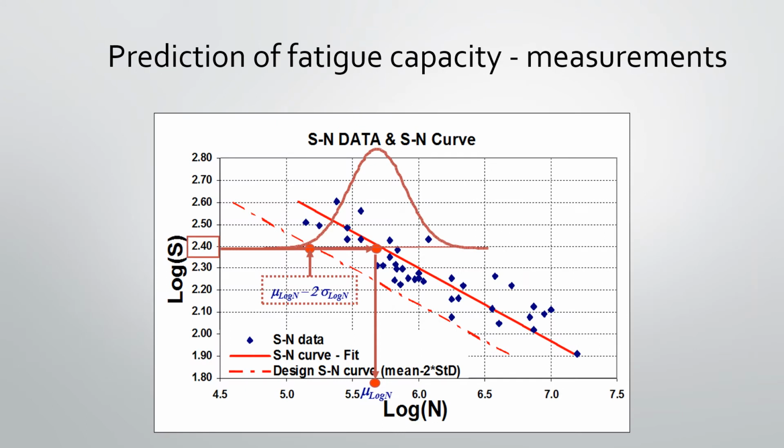The next problem is to plot the N in the SN curve. Failure is often defined, at least for tubular joints, as the point when the crack has grown through the wall thickness of the specimen. The problem is not so much to measure the number of cycles, but rather to figure out exactly when the crack is through the thickness. Visual examination can be quite unreliable, and a possible improvement is to define that the crack must be through thickness when the strain gauges at the starting point of the crack have lost all strain. This is more reliable, but still associated with a certain variation.